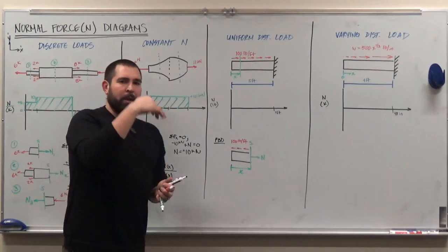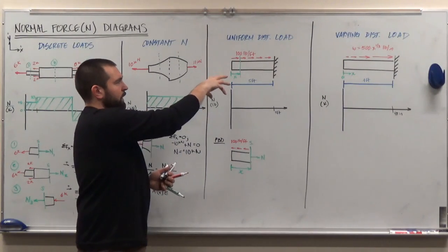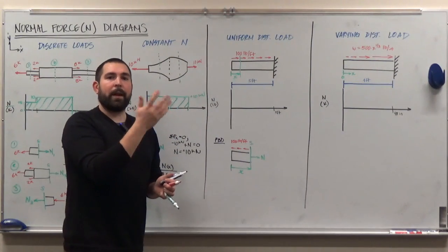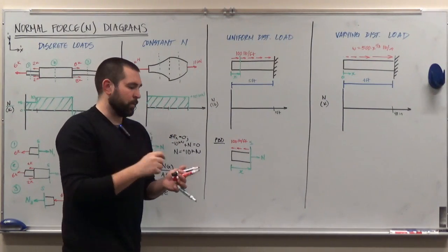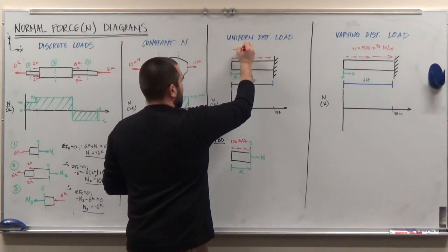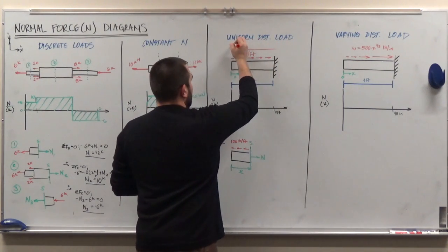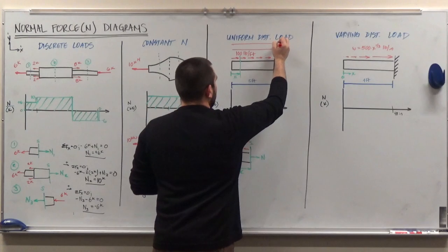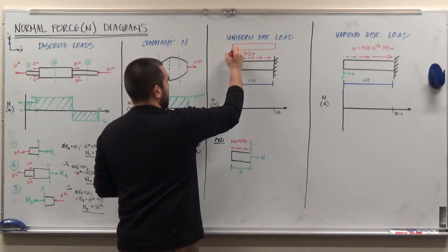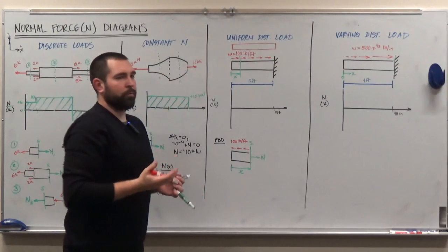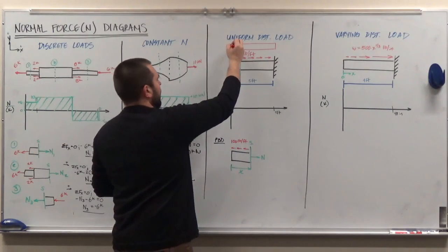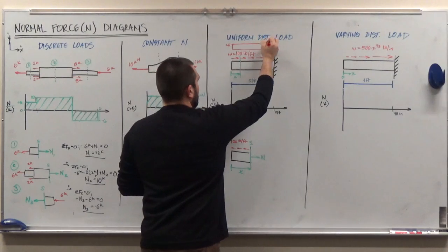So just like with beams and transverse loads, we can represent this loading in terms of an area, which is going to give us the resultant force. In other words, this is a uniformly distributed load, so it has a constant magnitude the entire distance. If this is what we call a variable w for a distributed load, I have a loading diagram that's just a horizontal line.